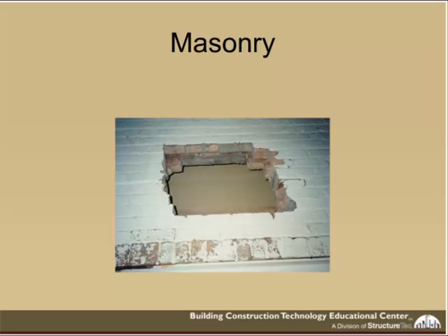Masonry that uses the mass construction type relies on the wall thickness to resist moisture intrusion. Masonry in general is a porous material, so the intent was to provide enough thickness so that the moisture could only absorb in so far before the rain event or whatever backed off and allowed it to start drying out again.